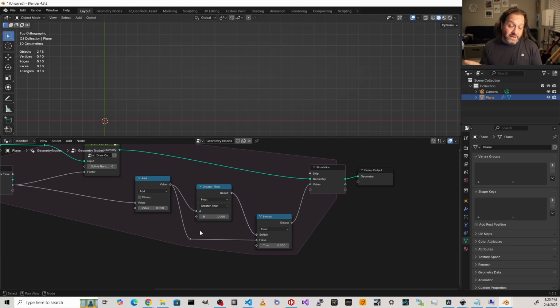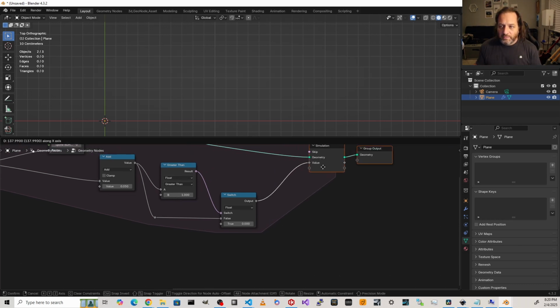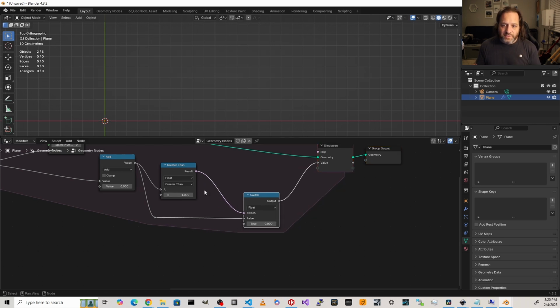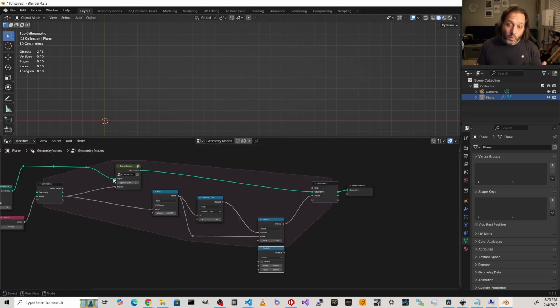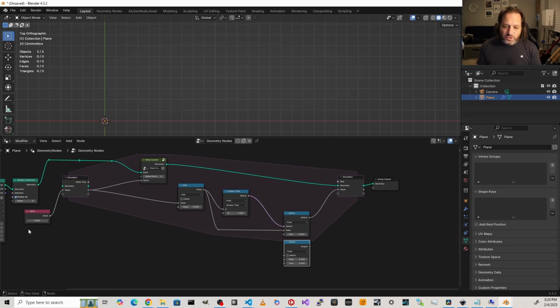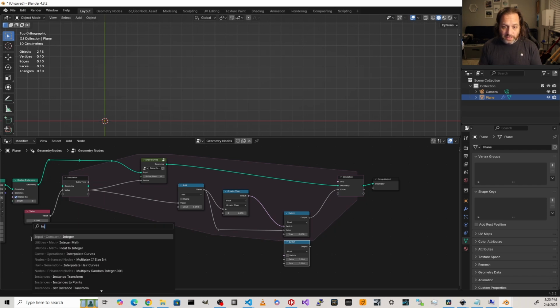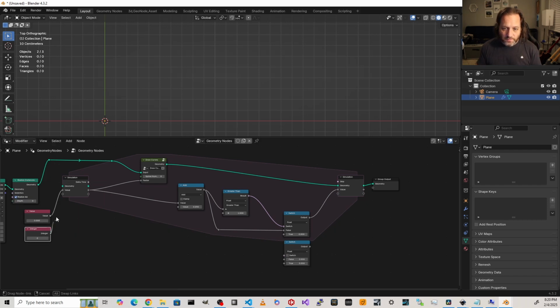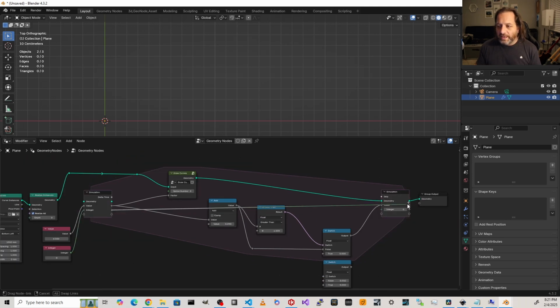As soon as it gets to the end of the curve, it's jumping right back to the beginning of the curve. So there's one other thing we want to do when we jump back, and that's increase our curve number. So we can use this same greater than, because that's our trigger, but we need to trigger something else. We need to trigger adding 1 to our spline number. We'll do the same thing we did for the factor here. We will add an input integer that's set to 0. We'll connect that to the output, and we'll connect that to the spline number on our draw curves.